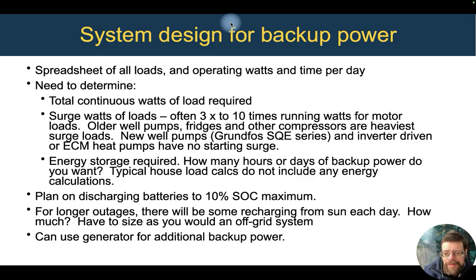If we have winter storms, maybe we don't assume very much sun for recharging. If it's in a time of the year where we typically do have a lot of sun, when we might have grid outages, maybe we can assume that we're having good solar input and good recharging from the sun each day. It depends on the particular situation. And with the setup of our inverter, we can also use a generator for additional backup power. We'll talk about that a bit later, as well as some of the benefits of that versus just using a generator.